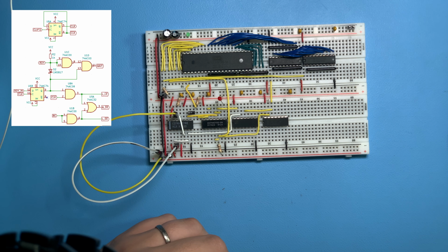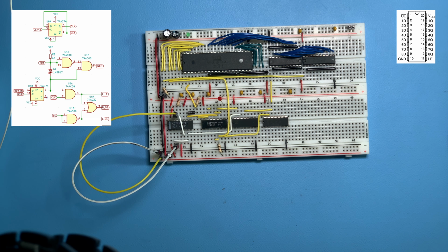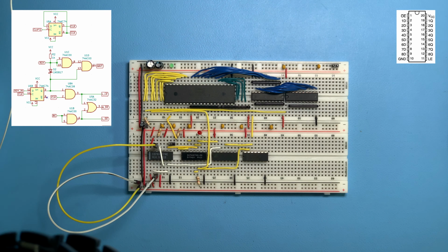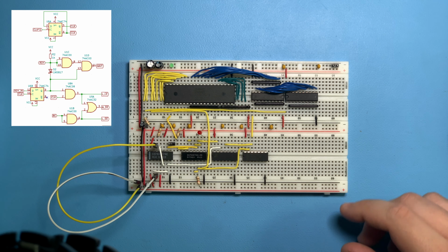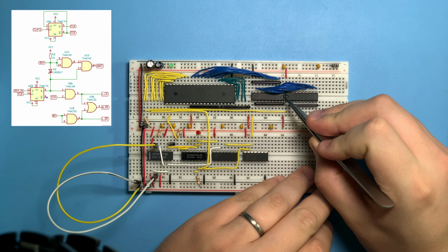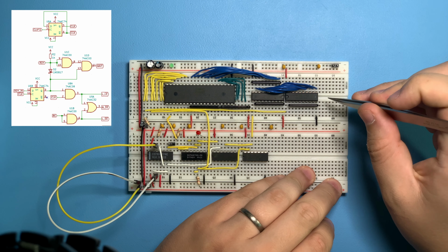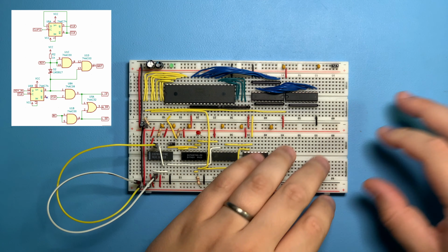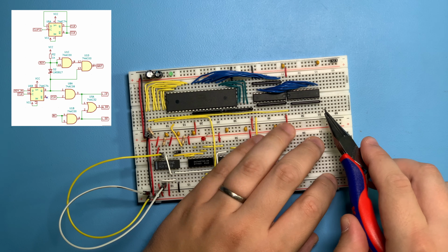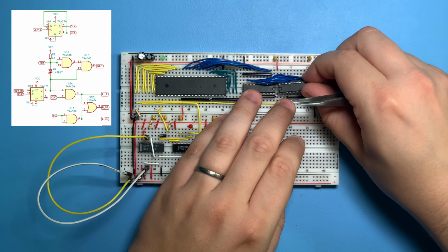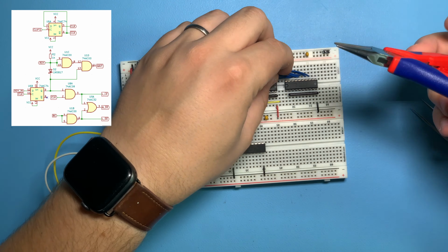From the inverted bus enable, we go to the output enable of the latch. And so that's pin 1 on the latch, which is all the way up here. So I'm going to shift this one over one spot so that I can go through with a wire between those two chips now that I have some space here. Let me go 2 spots.